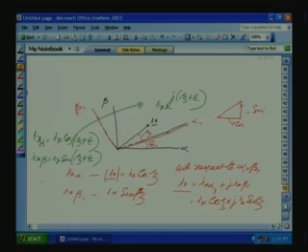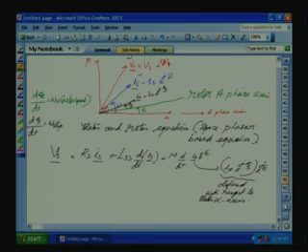Okay. So, when we transfer to this axis, if the movement is in this direction, the angle we are measuring in this direction is increased, theta plus epsilon. Now, if you have an axis somewhere here, then that angle has to be subtracted, depending on the rotation. So, in the previous case, originally the IR was defined with respect to the rotor axis. Now, we are defining it with respect to the stator axis, that is why e raised to j epsilon here.